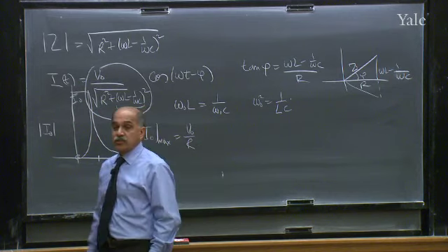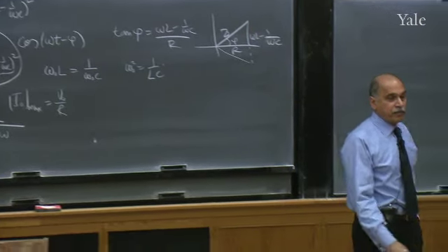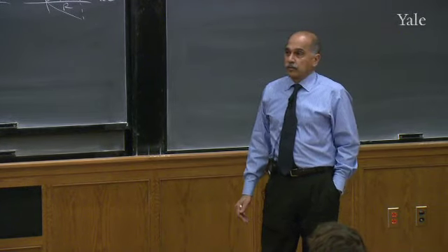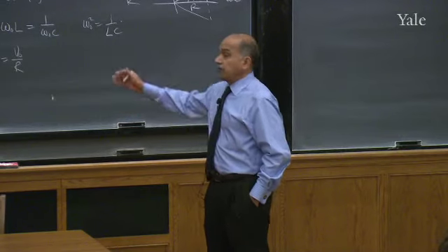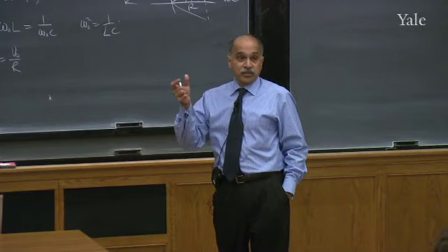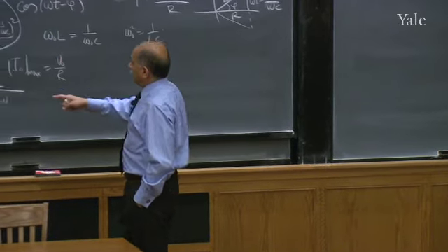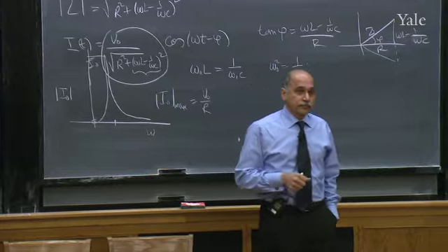It's as if L and C are not there. You have them there, but they're not doing anything. They've neutralized each other. So you can ask, why put something in that doesn't do anything? Well, first of all, it does something at other frequencies. Only at one magical frequency, they go away. But what is interesting is this very sharp response you have.